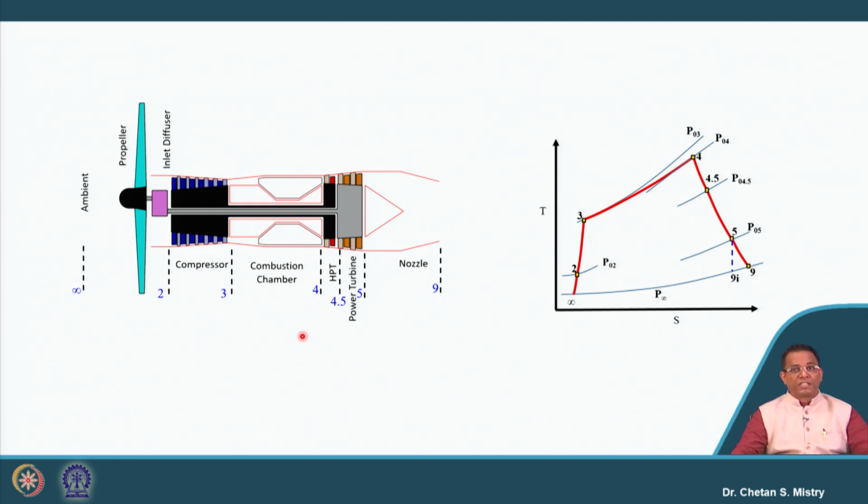Here, since a fraction is given, we need to take care of what we mean by our delta H. But be careful, this delta H is at different locations. My HP turbine is used to rotate my compressor, and my LP turbine is used to rotate only the propeller. So you need to be careful about this configuration. Let's discuss the hints, and then we will stop.